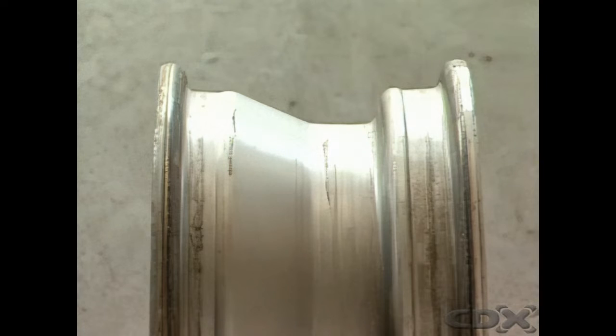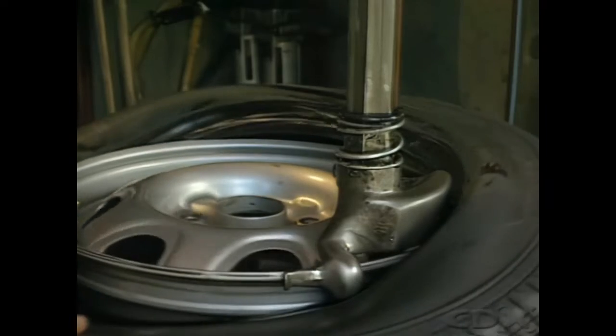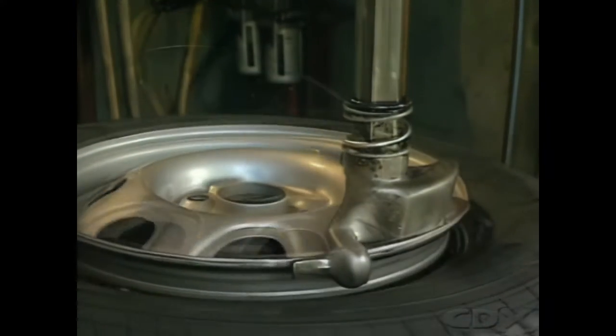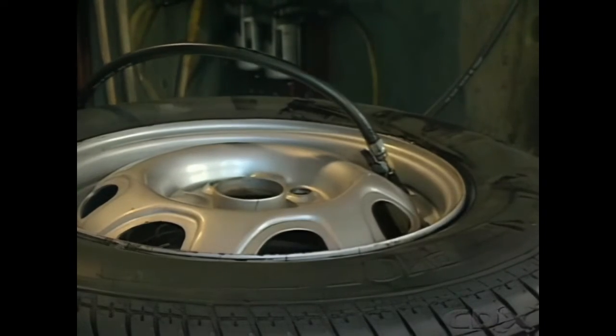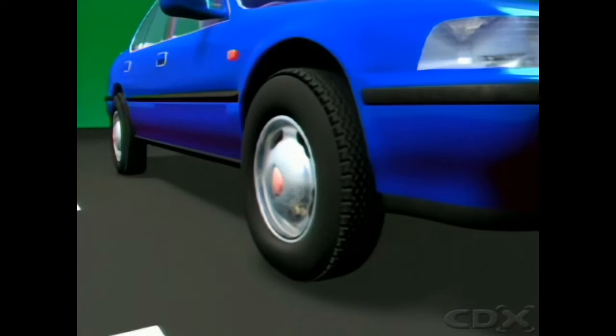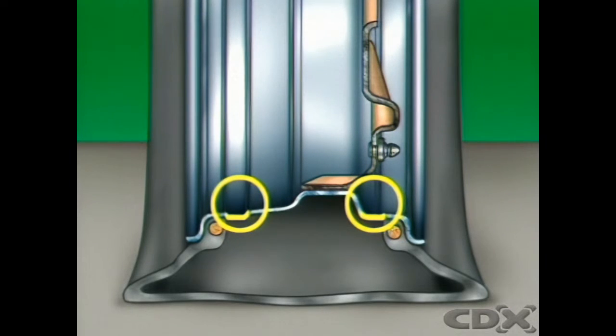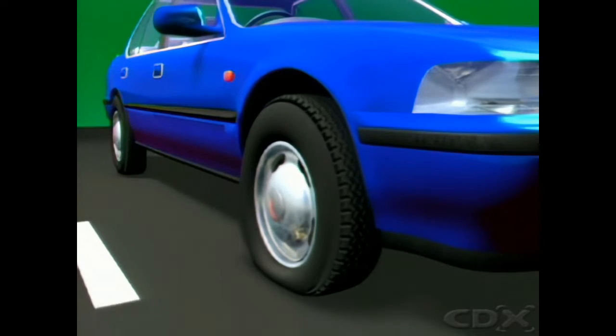Passenger cars normally use rims which are of well-based or drop-centre design. The drop centre is used for mounting and demounting the tyre onto the rim. When inflated, the tyre is locked to the rim by tapering the bead seat towards the flange, or by safety ridges or humps close to the flange. In the event of sudden deflation or blowout, safety ridges prevent the tyre moving down into the well. This helps maintain control of the vehicle while it is being braked.